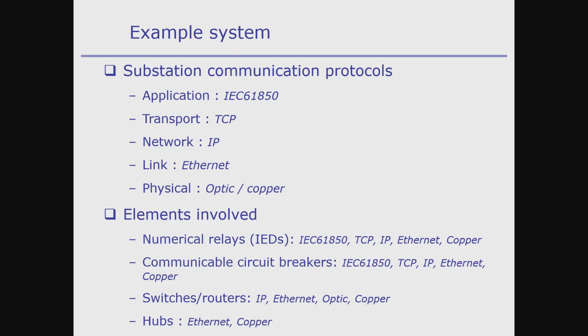Sorry? Yeah, routable GOOSE. You are getting ahead of me now. We will talk about that. So routable GOOSE obviously is using, but it uses UDP. It doesn't use TCP. It uses UDP. And UDP is better than regular GOOSE, but still not like client server communication. And obviously now you add time, right? You are going to add time because you are using UDP. Yeah.